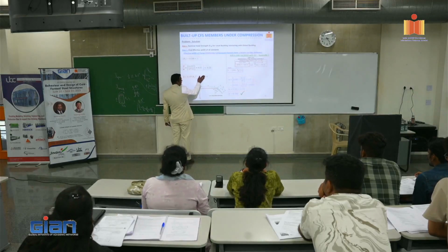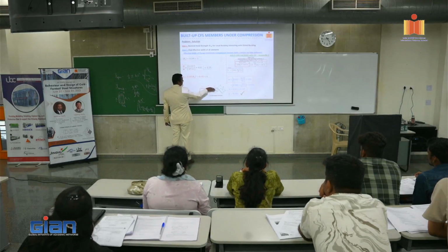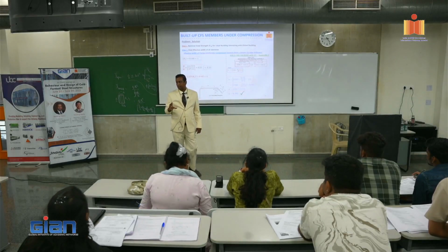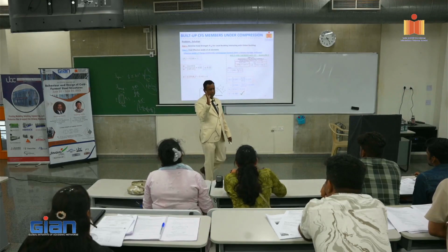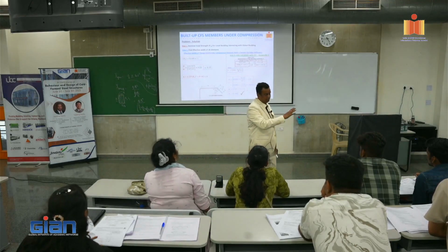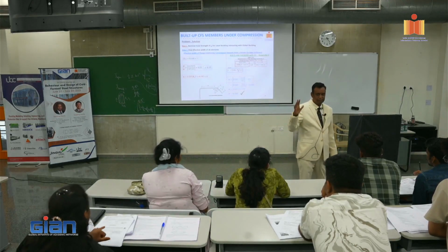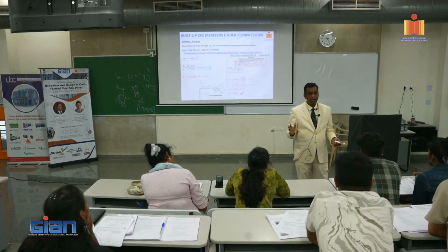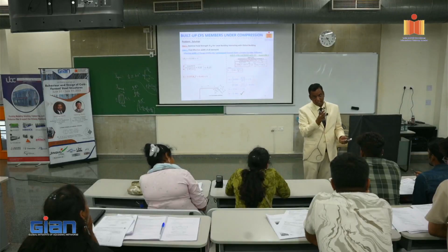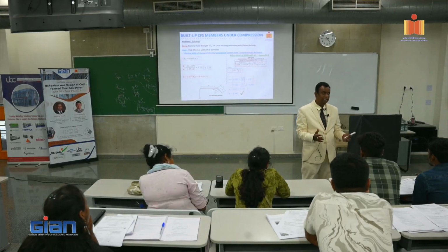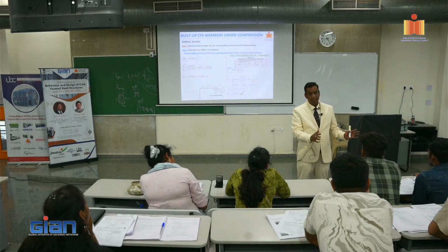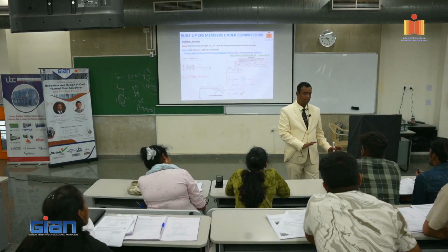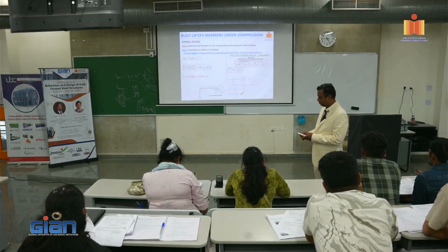Right? And this is the extra thing that you get because of this small stiffener. You understand? So it says that it's not 100% free, it is not 100% simple support, it is somewhere in between. Our job is to not neglect the depth of the stiffener. We take that and do some calculations so that we get some value of K which is greater than 0.43 but less than 4. Right?